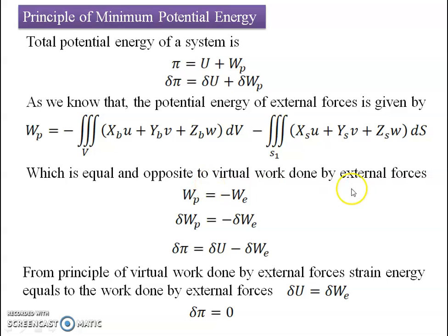If I apply the virtual work principle here, we see that there is an external work done by the applied forces. This external work done is nearly equal in magnitude to the potential energy of external forces. So we can say Wp equals minus We. Again, we can say dWp equals minus dWe, so the incremental potential energy will be equal to the incremental work done by the external force in case of virtual work done. That's why dΠ equals dU minus dWe.